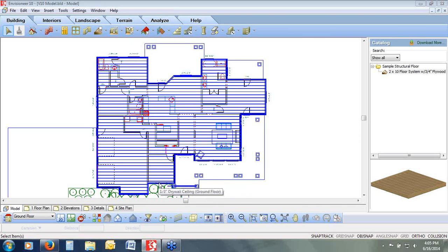And again, when you've selected that element, so I'm going to go now and select my structural floor, holding down that Shift key, I'm going to go through and cycle through all of the different objects that have this common edge, and you can see all the different ones. There's my structural floor. Notice all the arrows pointing to the different edges that I can select. Now that it's my primary object, I can move and select it and adjust it.